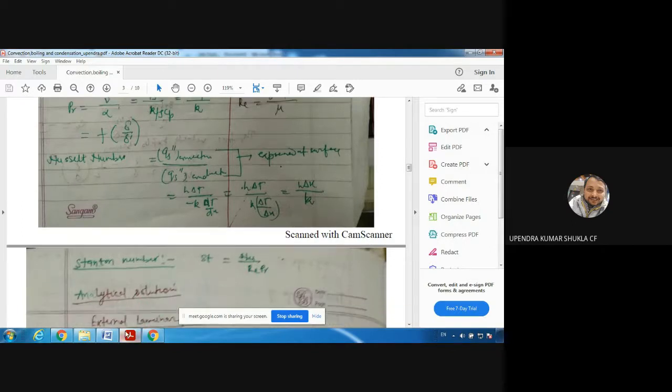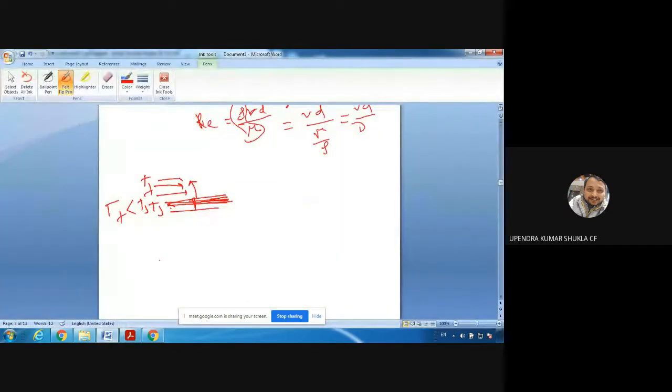So the Nusselt number is, if we write L in place of delta x, h L by k. Now if you know the correlation, you will find the Nusselt number, and then you must be happy because you will get the value of h right from here.